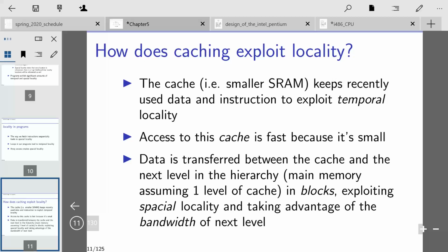One of them, for example, is memory consistency between the instruction and data cache. When you load a program or modify program space, it's almost like self-modifying code. When that modification is made, it's made through the data port.